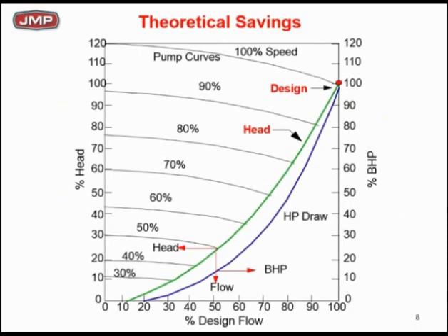But here's the problem. We have people applying this. We have variable speed drive people applying this. We have pump people who believe this happens in all cases, and it does not, because we have assumed here 100% variable head. This is where you've got to begin to think in terms of the future. Why are we not getting this much savings at half speed on most jobs? How come most jobs at half speed are not half flow and are not 12.5% brake horsepower, even though theoretically that says what you should have?